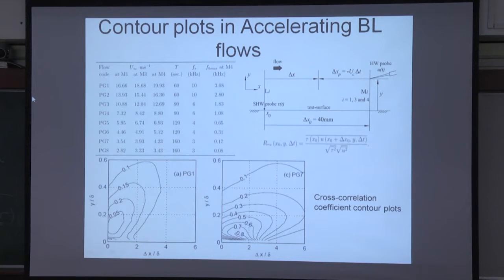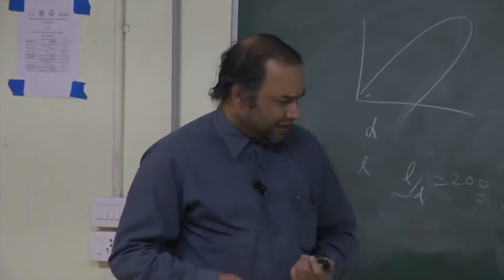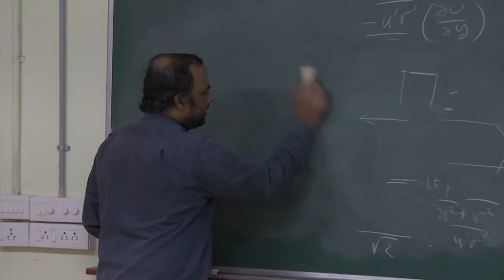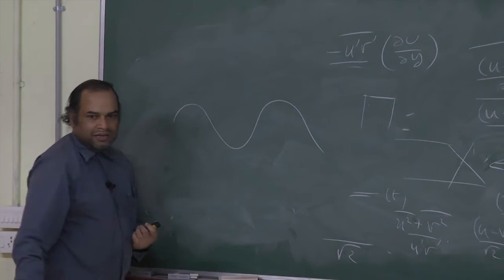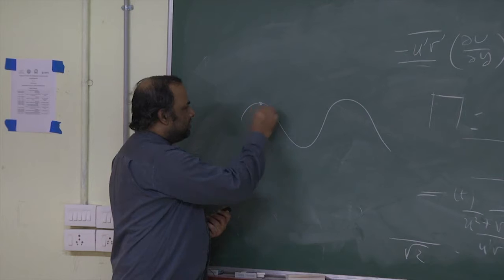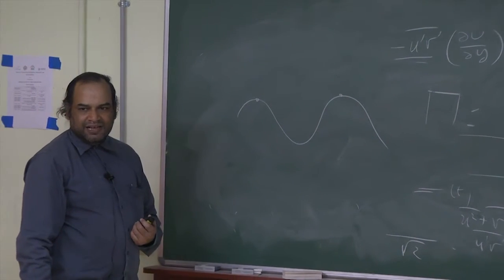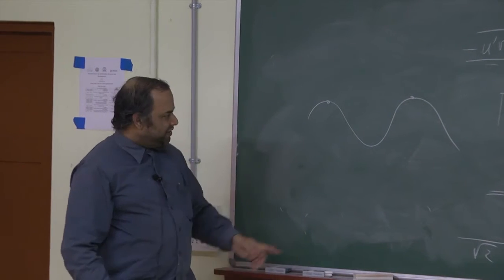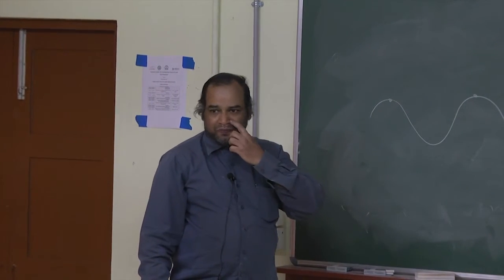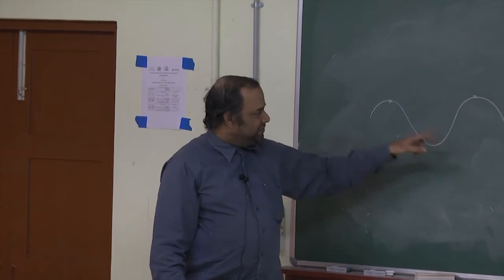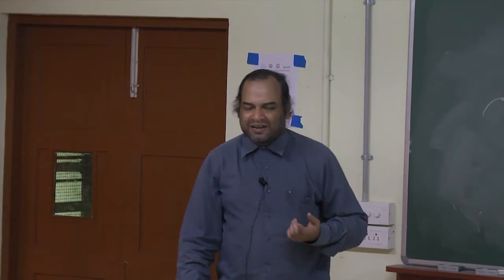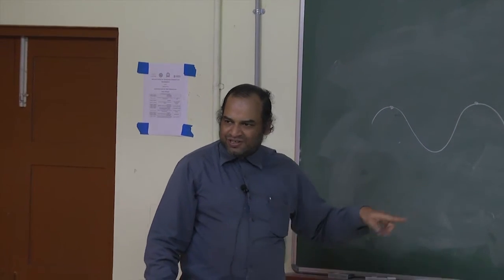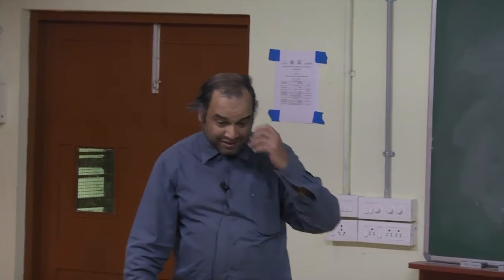I think it's best explained with the picture which I think TS drew in the morning, that's also probably a good one. So if you have a sine wave like this, and I am going to sample at only frequencies like this, what is it I am doing? I am trying to sample an event which has this fast time scale, with something which is a lot slower. Obviously, I am not going to capture that. I will get spurious frequencies here, which are not there in the original signal. You can have variants of this, but I think it's vividly seen.